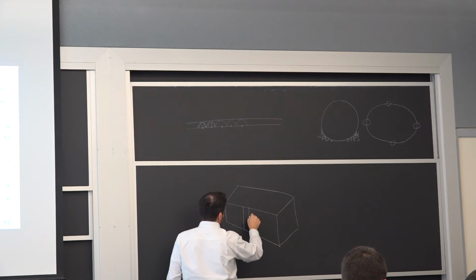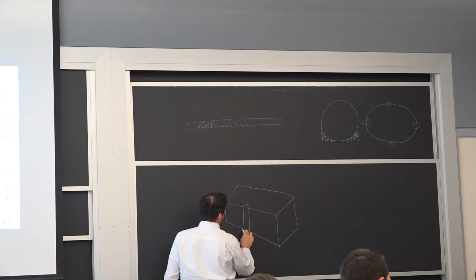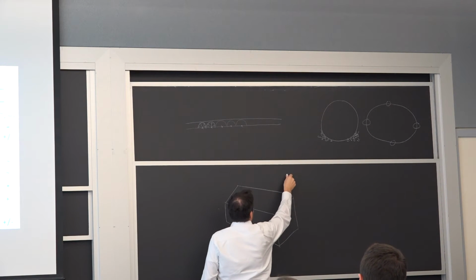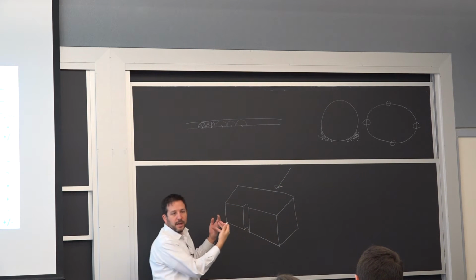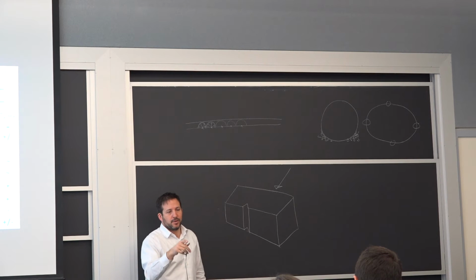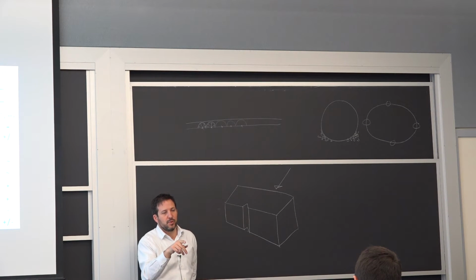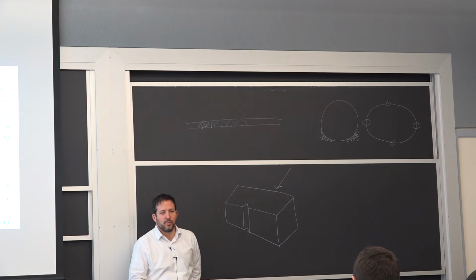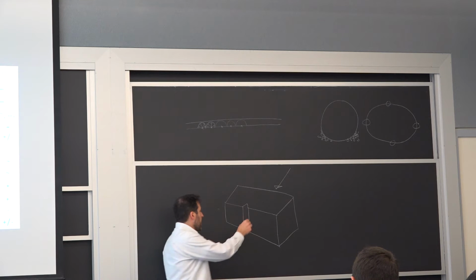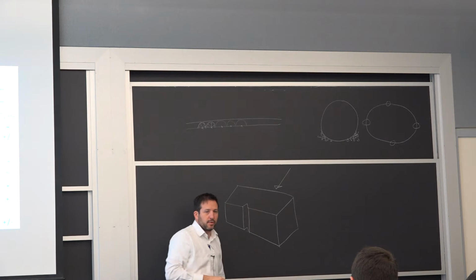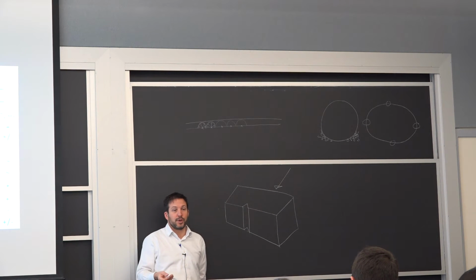So let's say we do a V notch. That's what is more common. So you take that off here. And then you hit it with a pendulum with a lot of energy this way, trying to open it up. Of the 3 samples I circulated, there's one case that's almost like a saw cut. There is no real deformation of the metal around here before the crack started and propagated across. So that's what we call a brittle behavior.